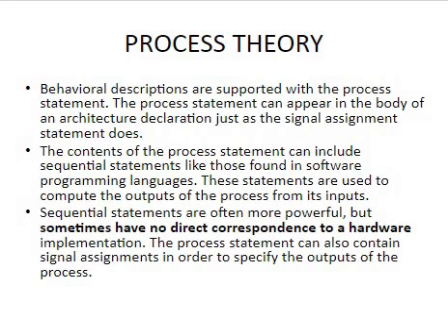Make sure that we use process mostly for sequential design, but it does not mean that if we use it for combinational design, we cannot. We can also use a process for combinational design, which we will see in later examples, where we will design logic gates using a process statement. The only difference between designing them using a process and a general program is that once they are designed using a process, the execution is sequential. So these statements are used to compute the outputs of the process from its inputs.